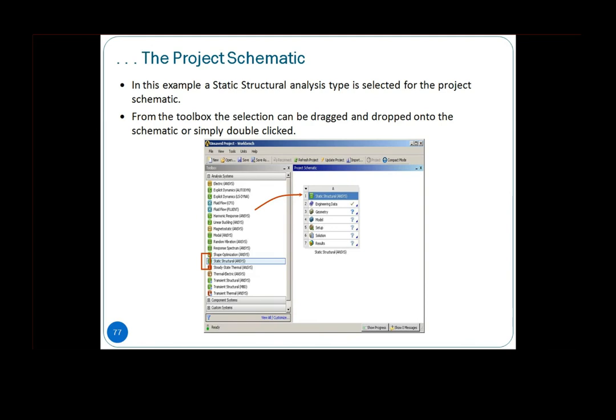You need to have the loading. You need to have the boundary, okay, how they're being fixed. Then you need to discretize it, okay, into elements. So all these setups have to be done. What I mean here is the pre-processing phase before you can send to the solver to solve it.